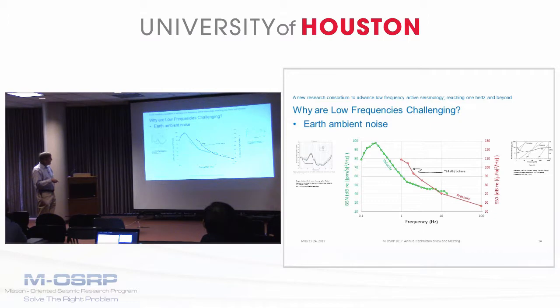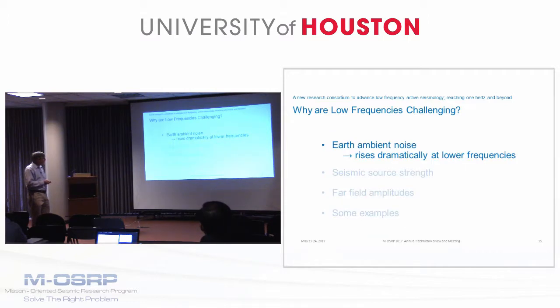So what I did is recast that data into another graph, into properties that are a little more familiar. So Gabrielson here is represented in pressure, and Berger is represented here as a velocity, and both plotted as a function of frequency. And of course, we're kind of interested in the few octaves around 1 hertz or so, and you can see that these slopes are very steep. And again, this is the best case scenario for noise. And in fact, some of these slopes are getting as high as 24 dB per octave. So we have that issue, which is a very important issue to deal with.